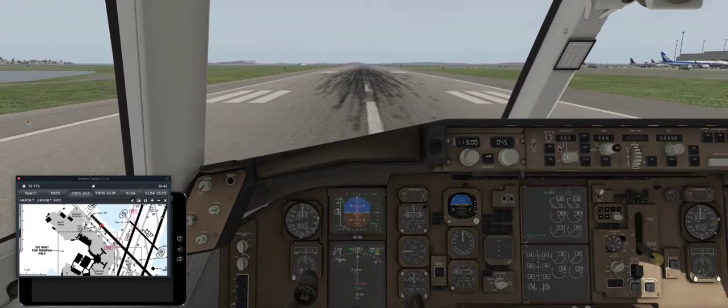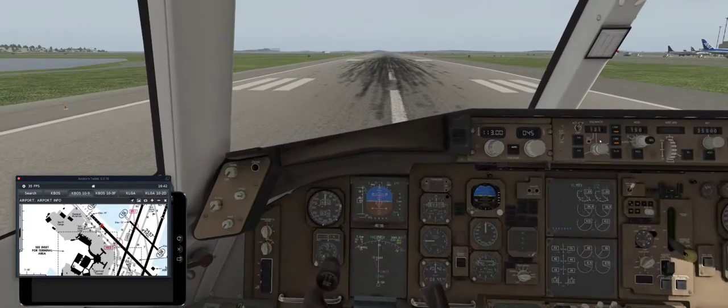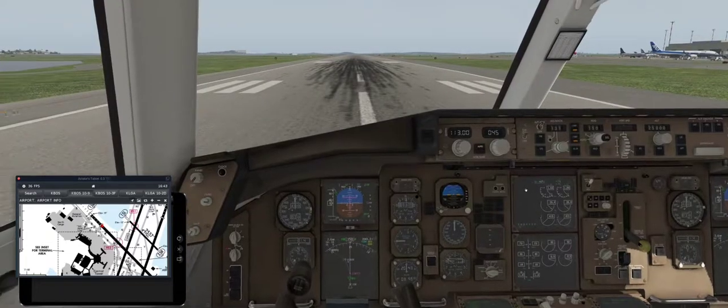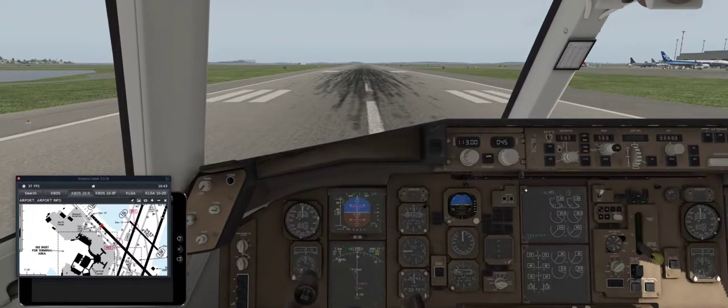We're going to set the brakes. We're going to select LNAV and VNAV. We're not going to command them. We're going to make sure our auto throttle's on, our flight directors are on, everything's ready. Engines healthy. No reason to think they're not going to work as expected.